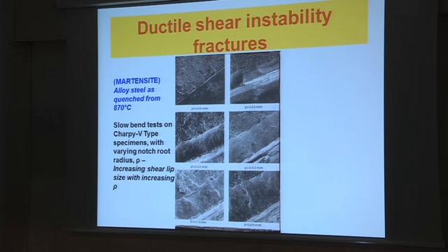If the strain hardening exponent, think of the tension test, you have the elastic side, then you enter into the plastic deformation region, and this plastic deformation region is characterized by the strain hardening exponent, which for the low carbon steels is between 0.25 and 0.30.